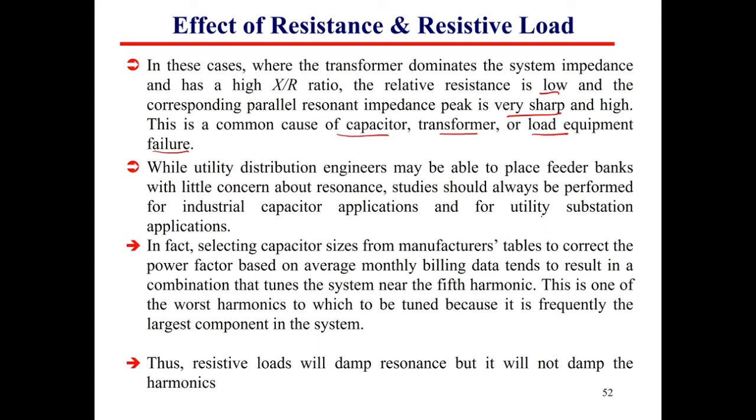And studies should always be performed for industrial capacitor applications and for utility substation applications. Again, if you place the capacitor bank near the transformer, that may cause problems. So you need to do a full study about that case in order to investigate what will happen to your system.